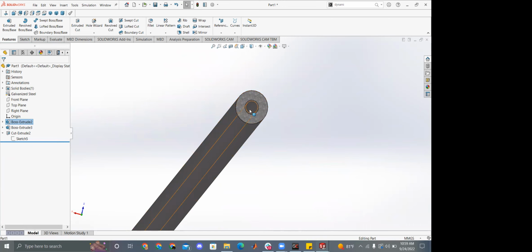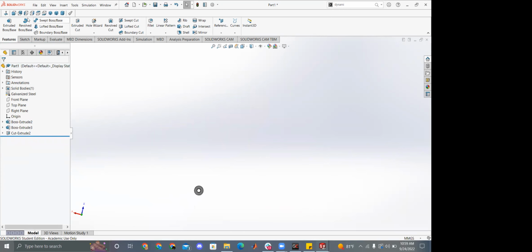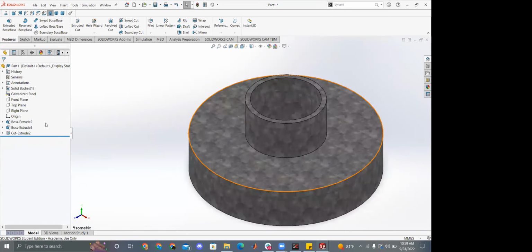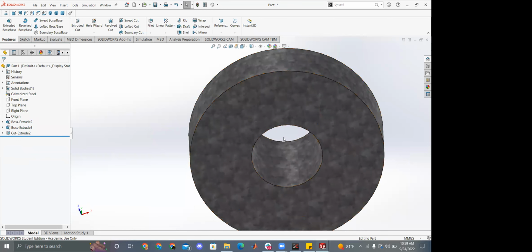So that's a really good practice when you're changing dimensions a lot. That kind of hole cut through a certain length can get overlooked really easily. If you set it to be to a certain surface and you constrain it geometrically rather than putting a dimension on it, it future proofs it a lot in terms of things you'll have to change. And then, as we said before, when you're rolling back, I'm going to make this not 200 millimeters tall anymore. If you want to put a feature in a place where you need to remove a certain feature, you can always use the rollback bar.